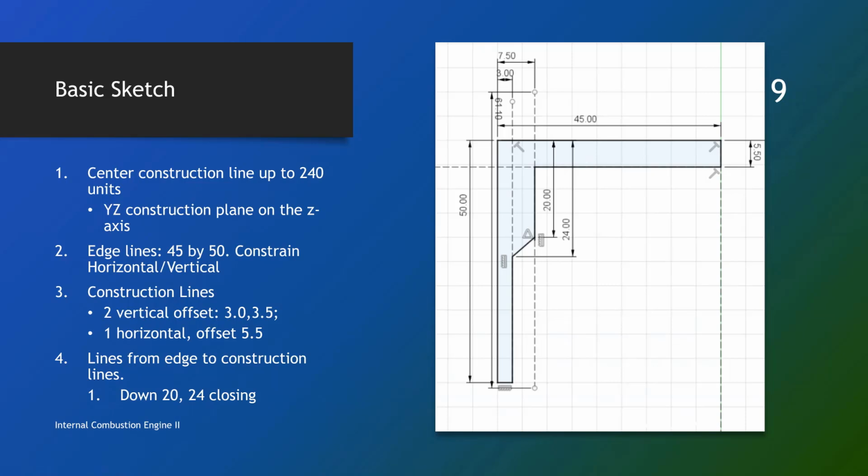That blue color shows that you can make a solid with it. That is, you can use that as a profile for an extrusion, for a revolve, for a lofting, for sweeping, and many other things you do in 3D. If it doesn't give you a light blue shade here, that means there is something wrong, it hasn't closed, and you have to work hard on that.